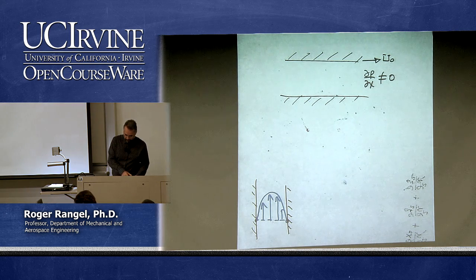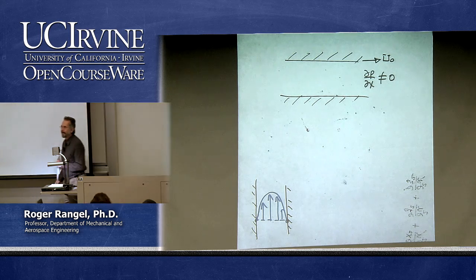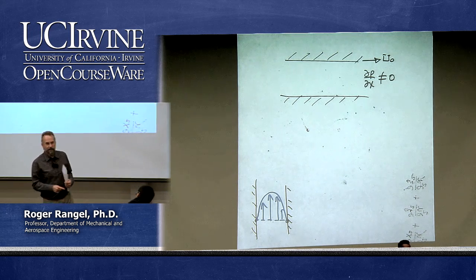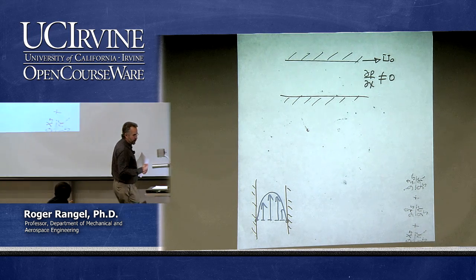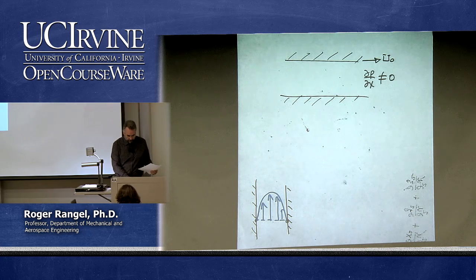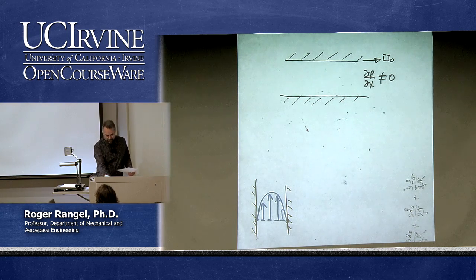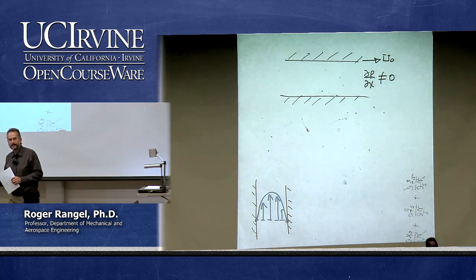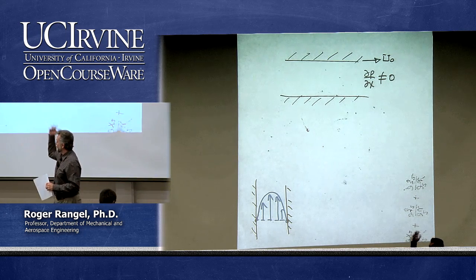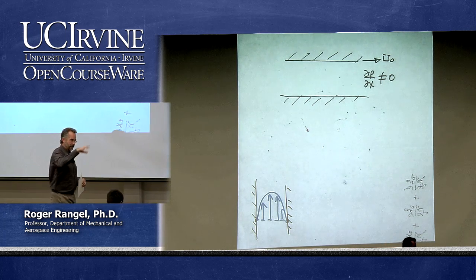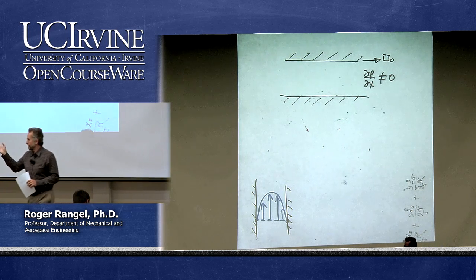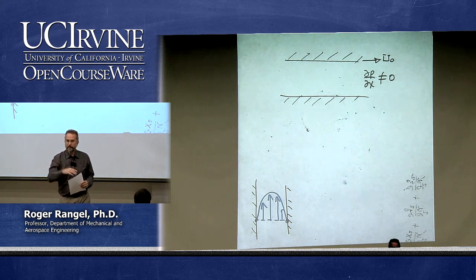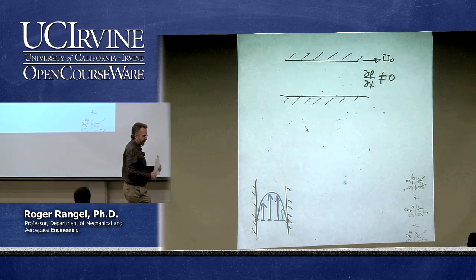How do I solve this problem? How do you think we solve this problem? Same way. Can I do something without having to solve them? Superposition. Why can I do superposition? We did it already, for example, when we were looking at the inviscid problems and dealing with the velocity potential, which satisfies Laplace's equation, you might recall. We could add solutions because we're solving a linear equation, which is Laplace's equation.